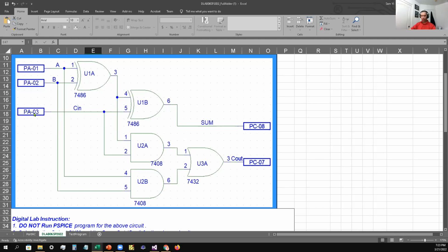However, when you're adding numbers, you get the carry. Now, what is carry? Carry means adding to the next column. So they're telling you you get 3 inputs: input A, input B, and also the carry, that's what they call a carry in. You carry to the next column, you have to add again, right? Okay, so this is a full adder.